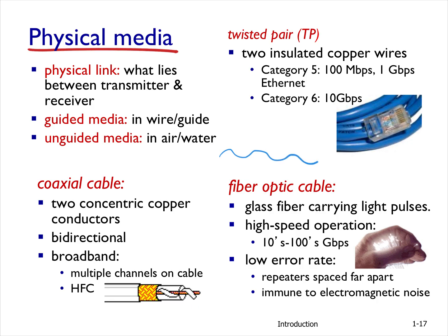There is something called twisted pair, 2 wires twisted, similar to what you use for electricity. You use the same type of cabling, 2 insulated wires twisted around each other between the source and the destination, and you send the information across that wire. Why do we do that? Why the twisting? Electromagnetics. Because this gives you better properties in terms of lower capacitance and lower inductance, and then you can reduce the delay. So your signal, which is typically a sharp step going up and down, will not spread a lot. But that's a totally different aspect; that's a study in electromagnetics.